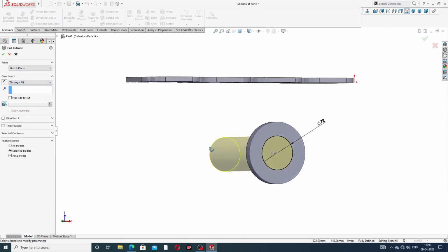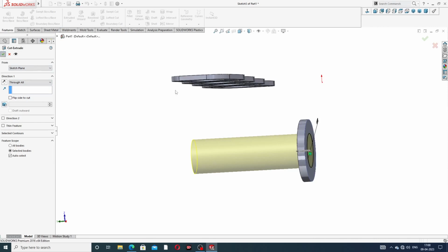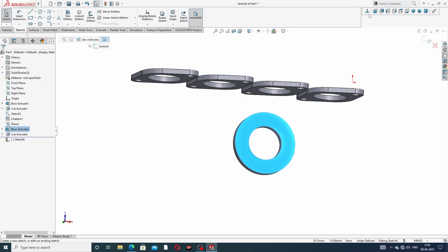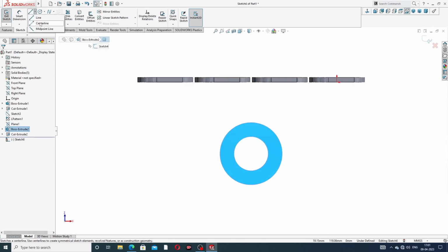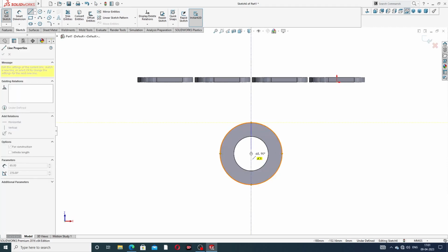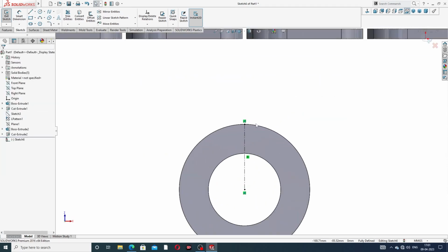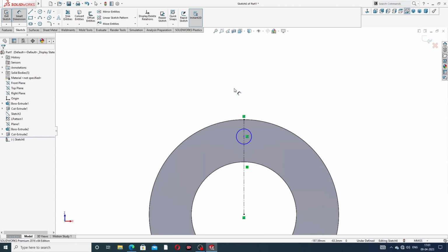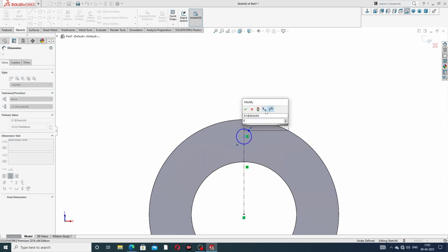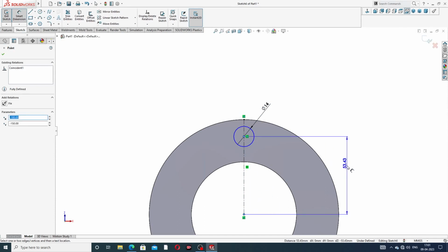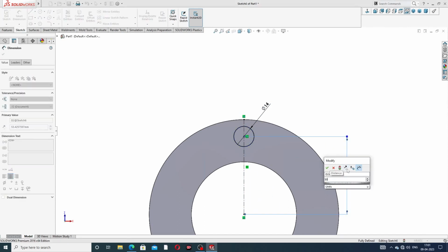use through all, and click OK, and again select this sketch normal and drawing a center line, and this center line is very important because some use pattern, and again click draw a circle, and circle diameter is 14 millimeter, and this distance to this is use 50 millimeter is perfect.